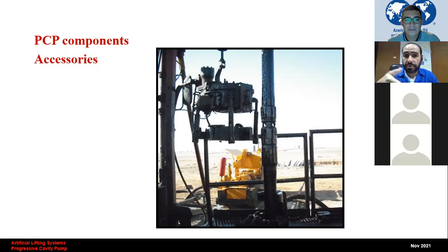If the rig just proceeded to pull the tubing in this situation, this means we will be having 30 or 40 barrels on the ground, which is a real mess. This will be projected and may cause a breach. So it's necessary to find some way to drain the fluids inside the tubing string into the annulus.